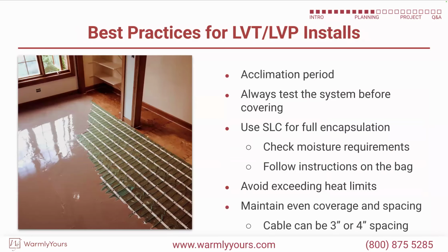And you can see right here what you're up against there. And if you look real carefully on this picture back here, you can see that there's like a white line here. And this is in the closet. So you can't heat closets, but we're running the self-leveling over into the closet so we have the same floor height all the way across the room. This is a run of caulk in here, so you're not getting that slurry going down into the walls. So you may notice that white line that goes around there. That's the caulk sealing up that gap there.